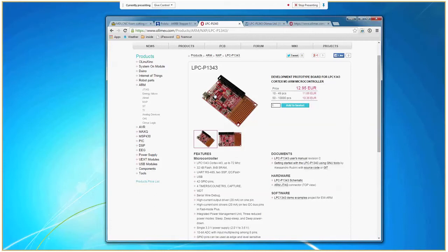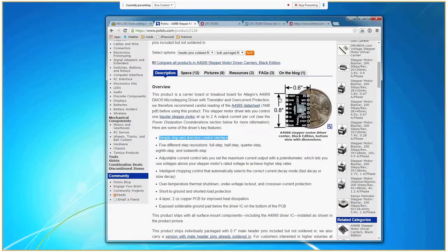And essentially you connect this board to your PC via USB, and then this prototyping area over here brings out all the I/O pins, and there's a wiring diagram so that you can solder wires or put a header on and make connectors to connect this to any sort of stepper motor controller that has this step and direction input. So there'll be 8 of them.